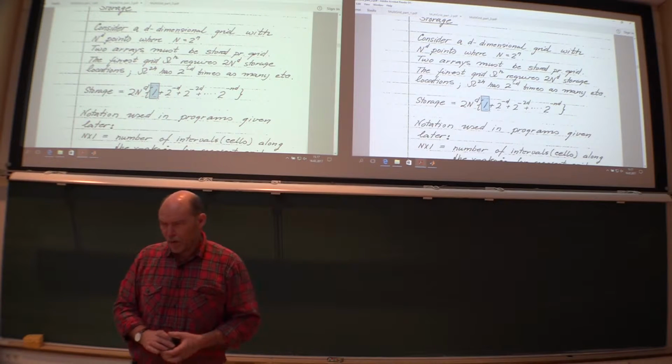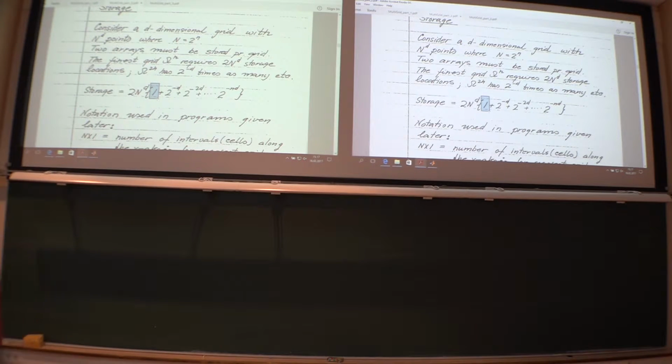But I mean, a one-dimensional problem, that's not realistic. We are talking, of course, always 2 or even 3D problems. And in 3 dimension, on the second grid level, you only need 1/8 of the entire memory storage from the fine mesh. So it's very economic when it comes to required memory. Very economic.